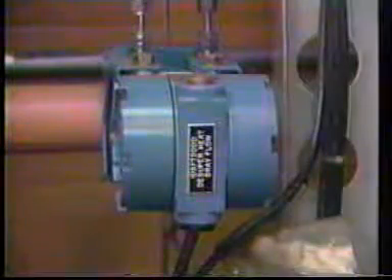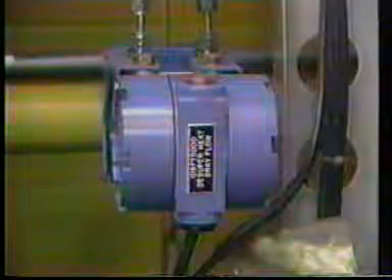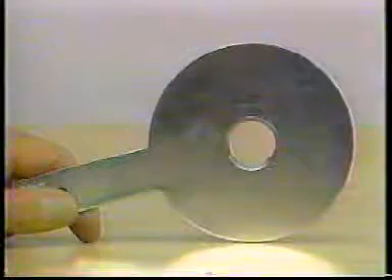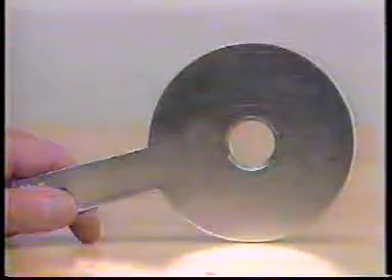All head-producing differential pressure flow meters work on the principle we've just seen. The primary sensing element constricts the fluid flow to produce additional dynamic pressure, while the secondary element measures the differential pressure. To convert this measured differential pressure to flow rate involves the use of a fairly complex mathematical formula. You'll find a copy of the formula in your textbook. There are a number of primary elements used to produce the differential head. The most common and the simplest is the orifice plate.